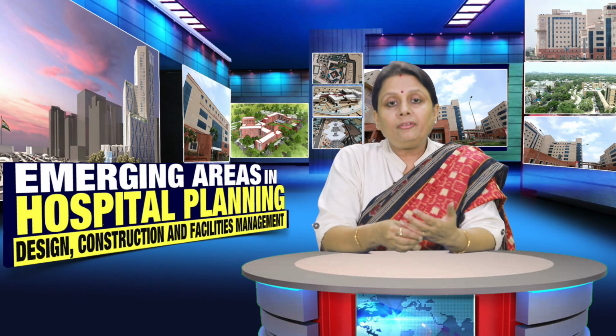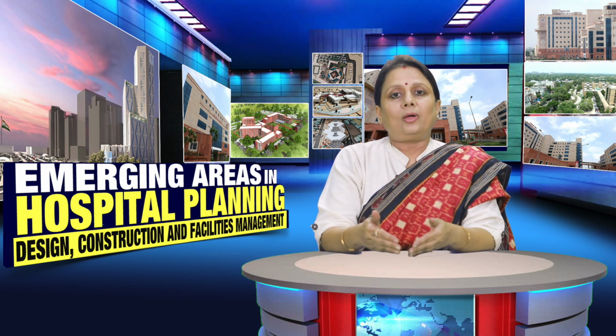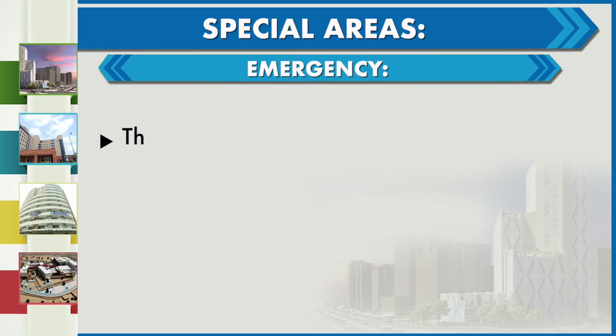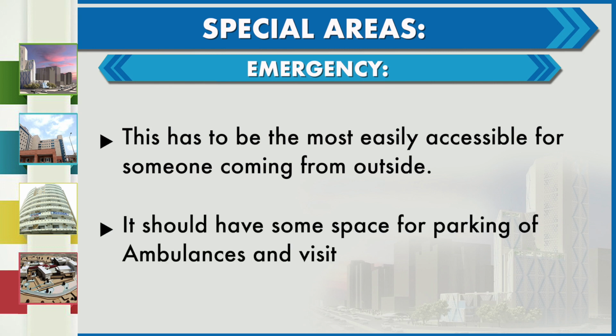Now, in a hospital, we have many special types of areas and we will discuss them one by one. The first very important area is emergency. Emergency has to be the most easily accessible area for someone coming from outside. It should have some space for parking of ambulances and visitor vehicles.